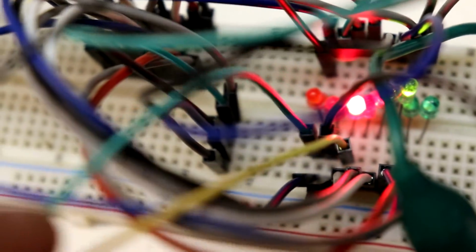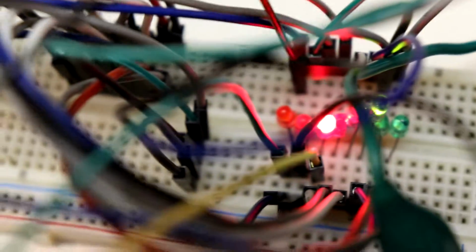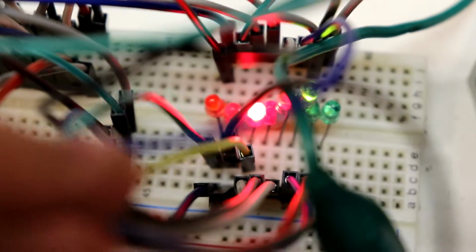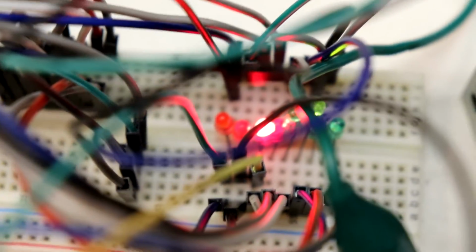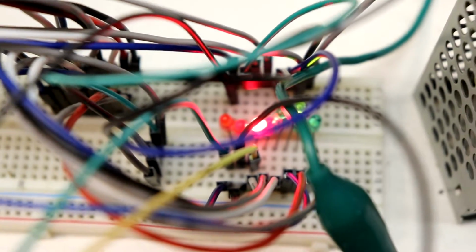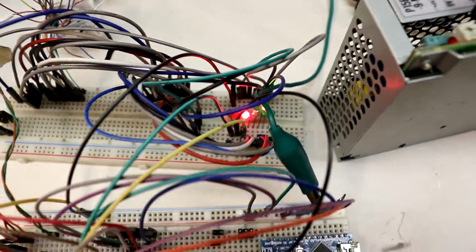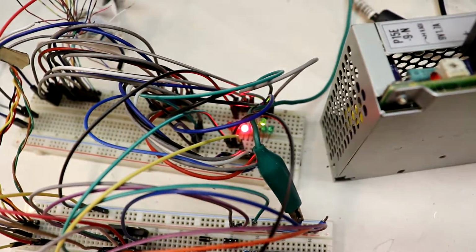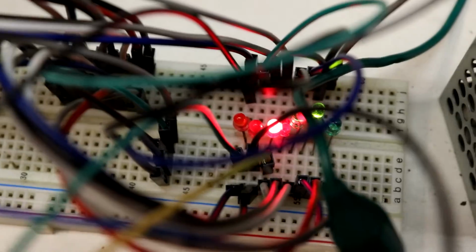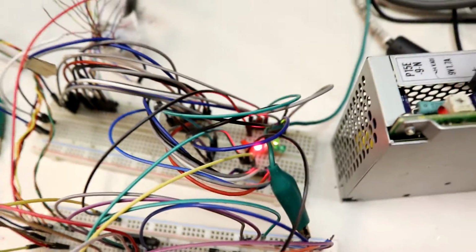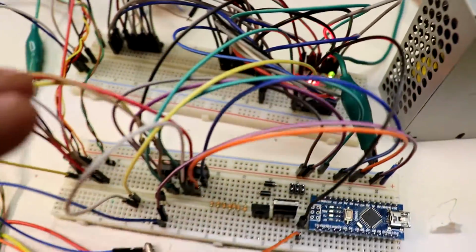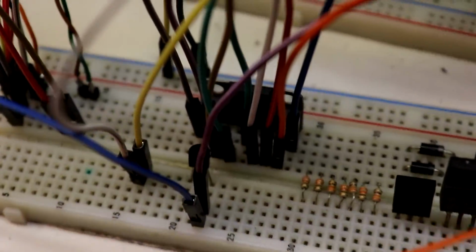So we left off at the signal wires that connected to the encoder sensor, and now I'll zoom in right there on this yellow and this green wire. They're connected to pins 2 and 4, and that middle blue wire, if you can see it, is connected to pin 3, the PWM signal. So basically I just found those pins by doing the same continuity test. And those LEDs, if you're wondering, are from a separate project, so don't pay attention to that. So pins 2 and 4 connect directly over to the motor controller.